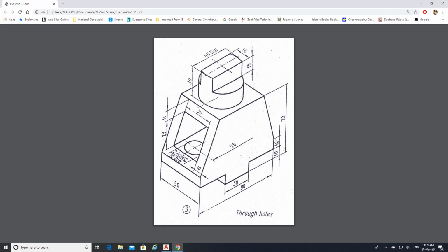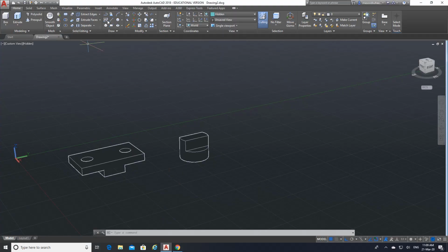What is this height? 50, 90, and then here it is 50. Okay, so let me go here, draw a line, 50. Sorry, I don't need this one. Sorry. I need to change the axis now. Here, get rid of this one. I need to change the axis, because Z is up. I need to put Z in this direction so that I can pull in that direction.